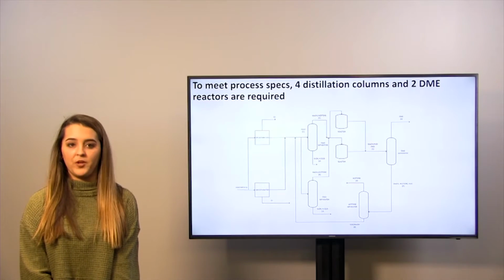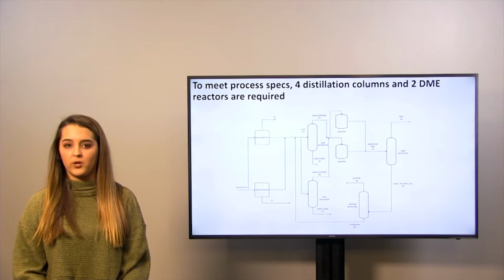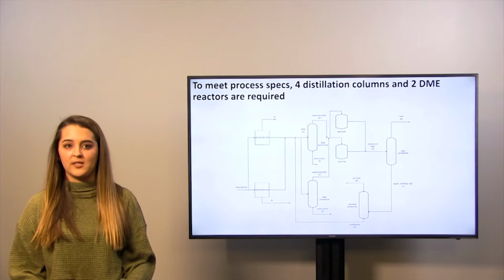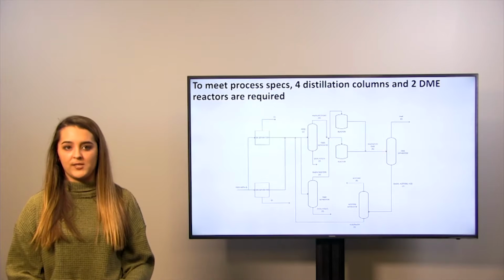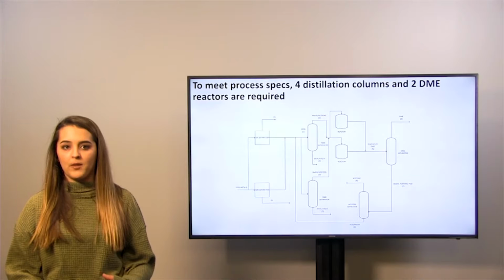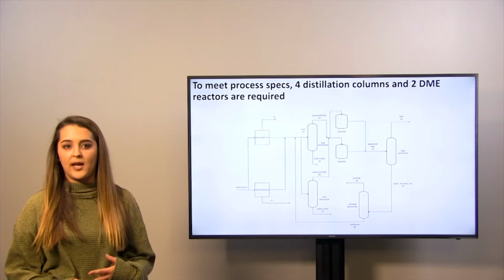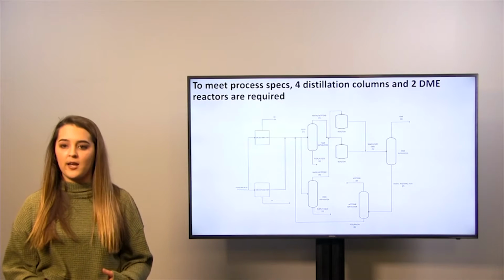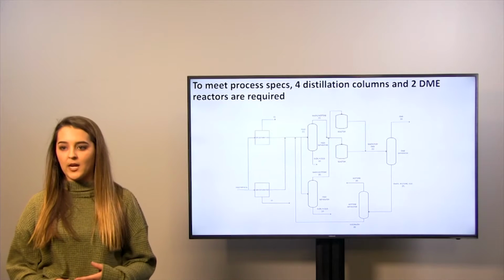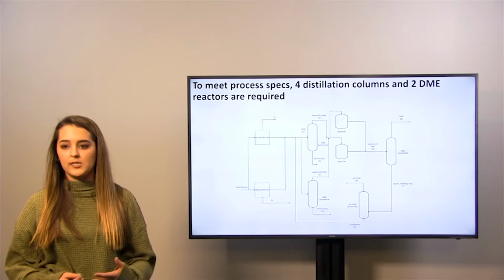To begin the process overview, the raw materials stream first enters an ion exchanger to remove the corrosive chloride ions that could potentially be harmful to the different materials of construction, specifically stainless steel. We had to decide on a resin to use, and we went with the Dowex Marathon A because it can withstand a relatively high temperature, and also because it exchanges the chloride ions with hydroxide ions. The hydroxide ions will react just to create more water, which is already present in the process, so it won't create any different types of reactions that we're not expecting, and it will be easy to deal with.